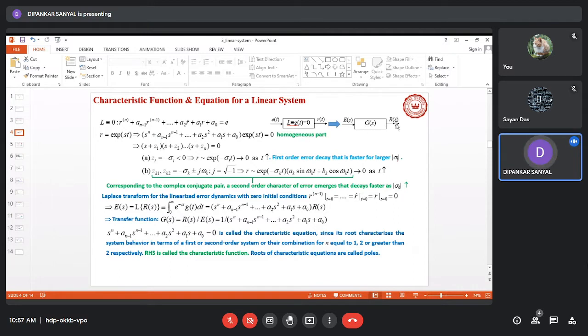If we have a feedback loop around this, with unity in the feedback loop, then the loop reduction would result in G(s)/(1+G(s)), and because of that, instead of a one here, what we'll be having is another polynomial in the numerator.